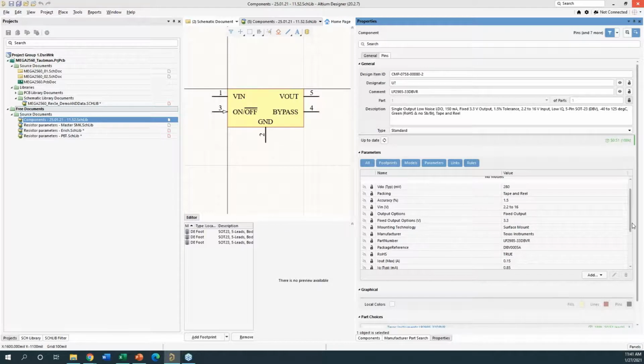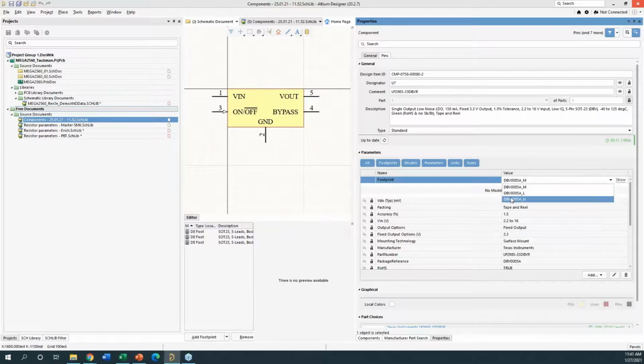In addition to this, it also does have a link to a footprint. So it knows the model. And of course, here they use the IPC one, so they show the M, N, and L here as well. So this is another way of obtaining a part through the manufacturer part search. So there are a few ways you can handle this over here.